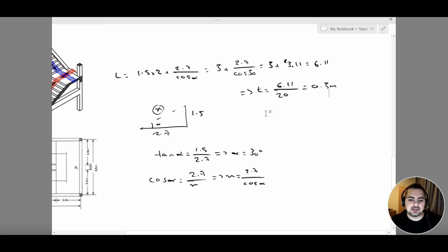Now, as a structural engineer that has a lot of experience on site, you would know that a thickness value of 0.3 meters is actually too big. It's not a convenient value. So usually when you follow the code, it gives you a value that will for sure 100% satisfy your deflection criteria and any check criteria that you need to go for.